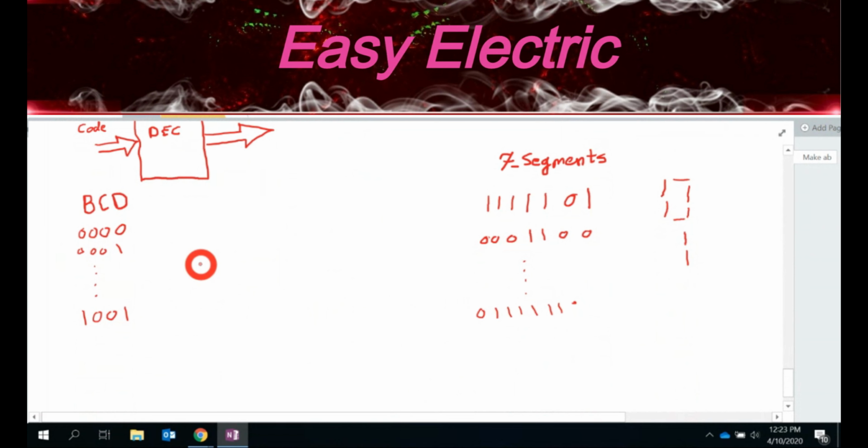So if I could do that with the code converter, it is exactly the good thing. For example, in the examples that we had in the lab, you have one adder that adds 2 4-bit numbers and gives another 4-bit number, which we usually show on LEDs as a BCD. Then we need to convert this to decimal to see whether the add or subtraction is right or wrong. So it is nice to connect the BCD codes to the code converter, get the 7-segment codes, connect that to the 7-segment, and exactly see that number on your 7-segment. Okay, this is the goal.